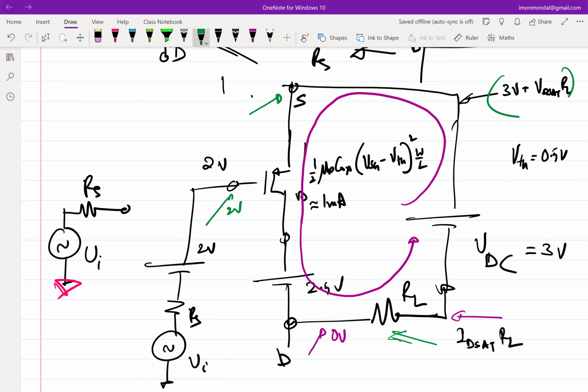So once you decide a bias point, you don't want that bias point to get affected after you have added extra connections to get it to work like an amplifier. So even though in the small signal model this way of connecting RL will actually work, when you put everything together you will run into the problem that you are trying to satisfy the incremental model, but the quiescent point is getting affected.